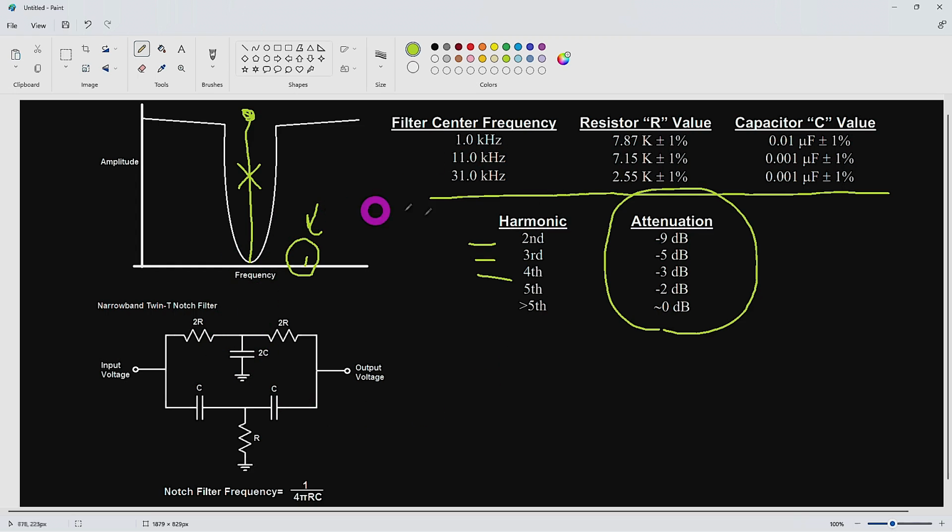But don't take for granted that any resistor and capacitor will work fine, because if these generate second harmonic also, it doesn't matter that they're filtering the fundamental, they'll leak the second harmonic into this, and you would basically end up measuring the filter instead of measuring the instrument. This is typically what happens when you push so far into the extreme edges of pretty much any kind of measurement, whether it's noise or linearity or voltage or current or time. It doesn't really matter. You always run into these unusual situations.